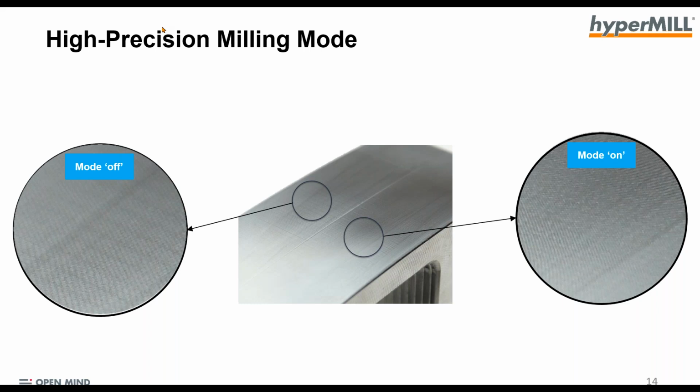But that could affect the surface quality. With the high precision surface mode, it redistributes the points, as I said, to the true surface. But if there are holes and gaps in the model, then the fail-safe is still the polyhedron. Okay, very important. You still get absolute safety with the best surface quality. It's a win-win. I'm just going to take you through to the model.